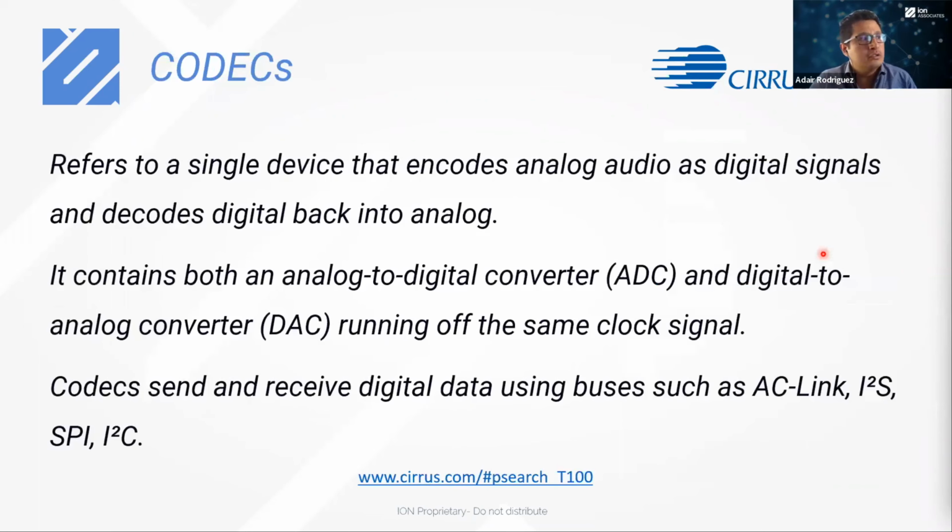With Cirrus Logic, inside an audio component, we will also find the codecs, which are more integrated devices that include analog to digital and digital to analog converters, also running with digital commands and communicating with external devices through digital buses like I2S, SPI, and I2C.